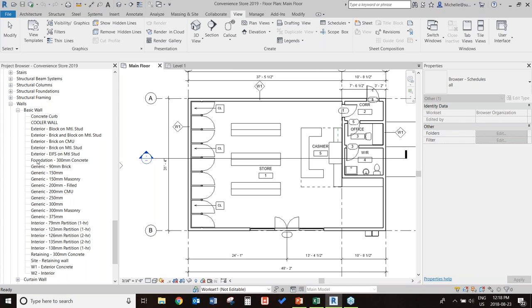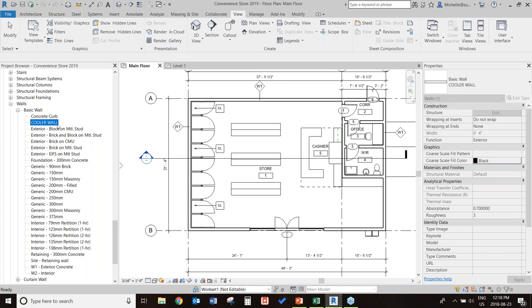So compare this up against the ones that you have in the warehouse file. Maybe just take screenshots, compare project browser to browser. Some of the ones that have been created, you'll find generally if people aren't following the naming convention, they will jump out. So again, it's a comment of saying, why didn't you follow the naming convention on this? Was it unclear? Were you unsure? All that stuff. But then after that, you can think of, well, was this wall something that we can reuse?